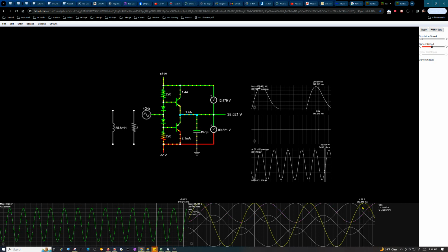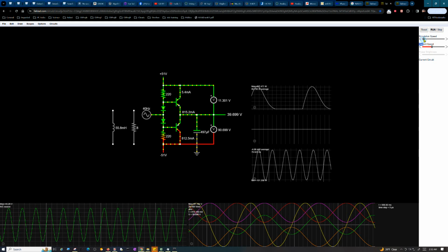And again, some of this may be because I can't drive the signal to the full rail. I have a feeling that's why there's a little discrepancy between what he's saying, because basically what he's saying is true. This is the point where you've got 50, in his case 40 volts, but in my case 50 volts across the transistor. All right, and that does correlate with peak current occurring there. The thing is that since I can't drive this transistor fully on, there's always at least an 11 or 12 volt drop across it, which you can see if I speed up the simulation.